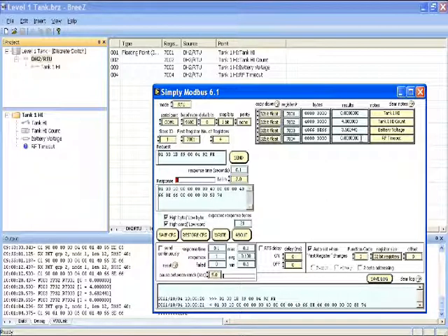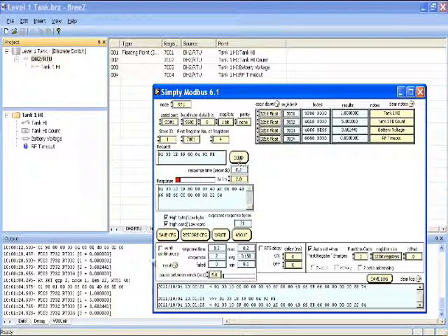Now I have switched the switch again. You notice the RX packet comes in to the debug of the DH2. Now I will send the request again. Notice the response go out to the Modbus master, and 7001 has changed to a 1, and count has gone up to 5. And on your master side, you can confirm that as well.